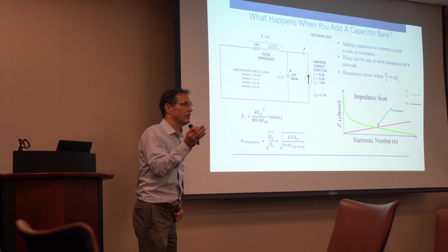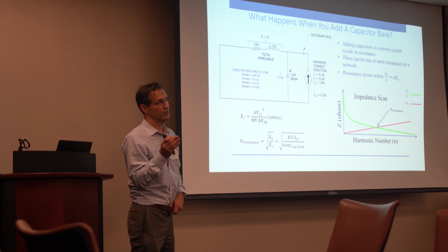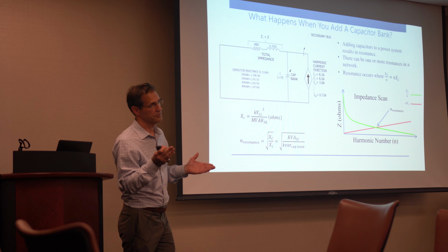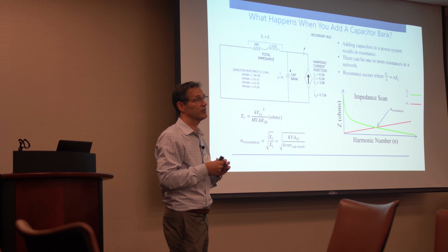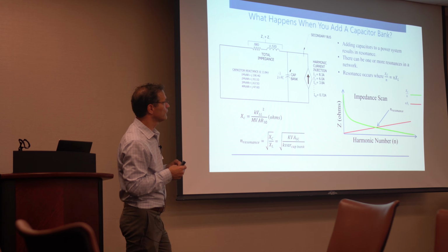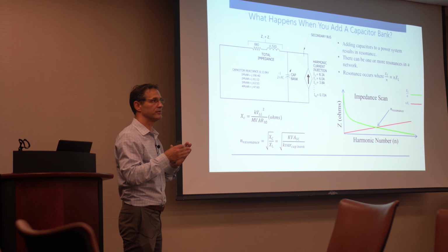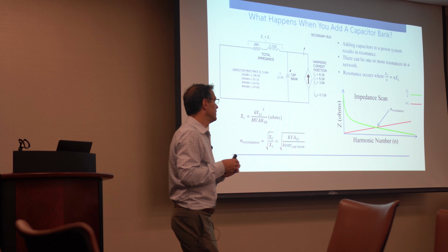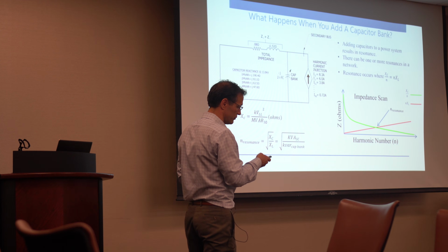Once you get down to the 11th, I think you're sunk, in my opinion, because there's 5th, 7th, 11th, 13th harmonics. You're going to have to do something. You're going to have to be concerned about resonance. But at higher frequencies, there's sometimes bigger gaps, and you don't have to be as worried about it. Anyways, we're going to talk about those worries in a second.